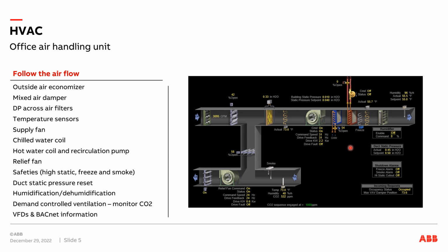For me to walk to one side of the building, get the roof access, walk all the way back to the other side of the building, it's darn near a 10-minute walk, and then you'd have to start troubleshooting. But the beauty is if you can see what caused it to trip off here, you can start troubleshooting before you even have to get on the roof. So that's the nice thing about these building automation control systems, it just brings so much data to you and really helps you troubleshoot.